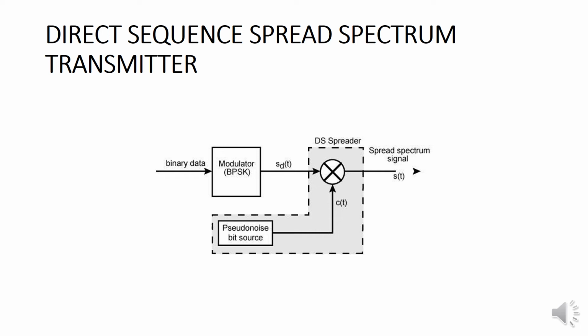The receiver demodulates the received signal y(t) with the carrier to move the spread spectrum to baseband, and after passing through a low pass filter the signal is recovered after despreading. Since both spread spectrum and BPSK modulation are linear operations, their order can be switched to make the problem easy to solve.